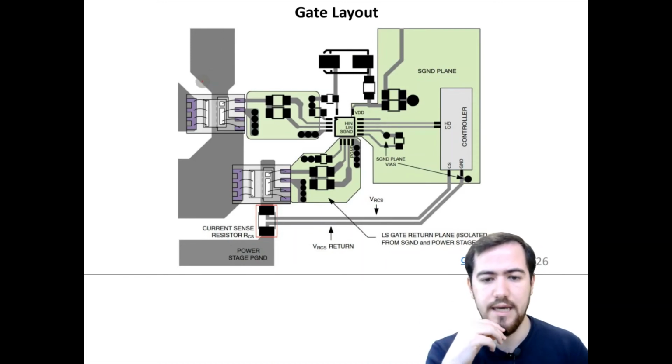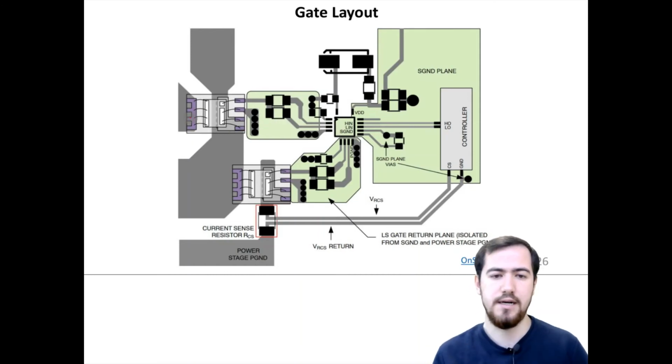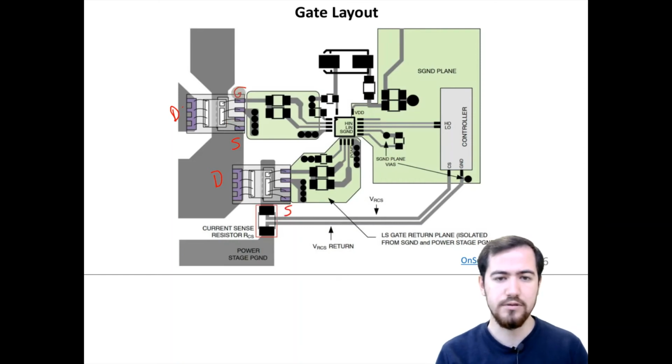This is an example layout design of a half bridge, and the high and low side switches are driven with the same gate driver, which includes an isolation inside that gate driver IC. So let me describe the pins of these MOSFETs. These pins are the drain pins here as well, and these lower two pins are the source pins, and we have a gate pin on the top, and this is the SS pin. The middle one is the SS pin, which is called the Kelvin source. Let me draw the symbol of this MOSFET as well.